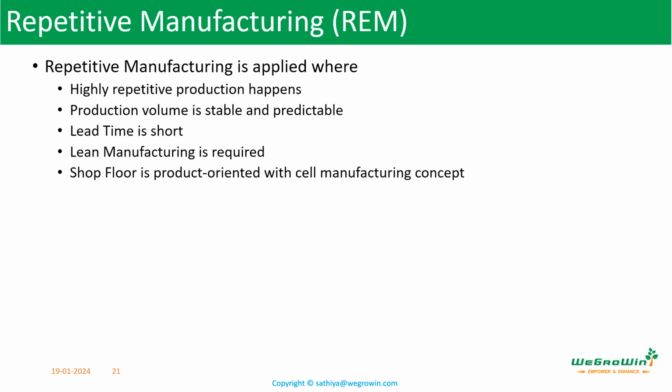In addition, we may consider implementing repetitive manufacturing when the following are true. You produce the same or similar products over a lengthy period of time, and you do not manufacture individually defined lots. Instead, total quantity is produced over a certain period of time. Your products always follow the same sequence through the machines and work centers in production. Routings tend to be simple and do not vary much. If these four conditions apply, then repetitive manufacturing can be applied.